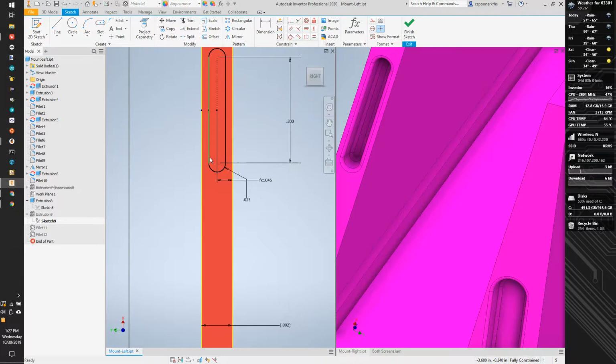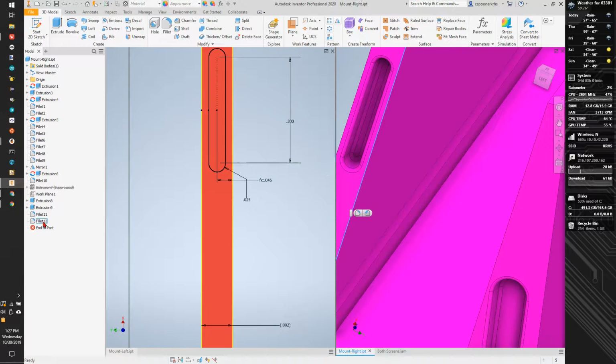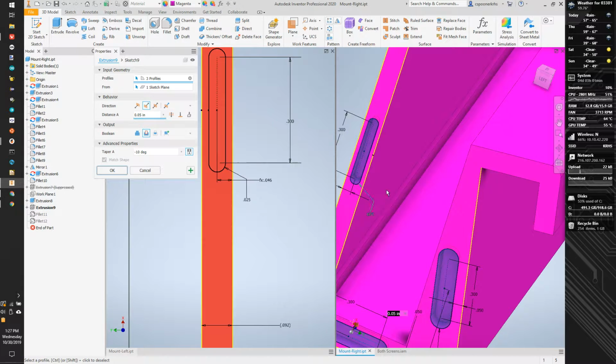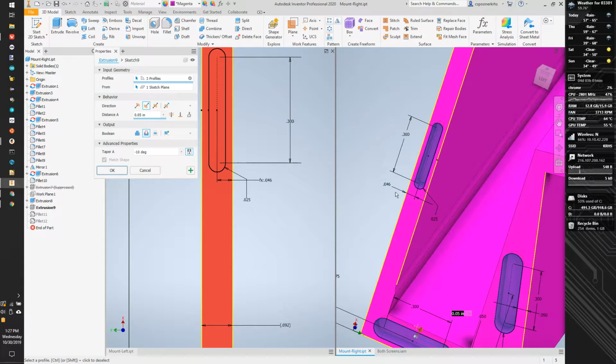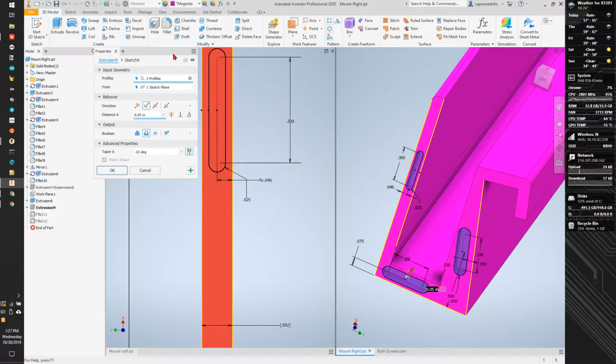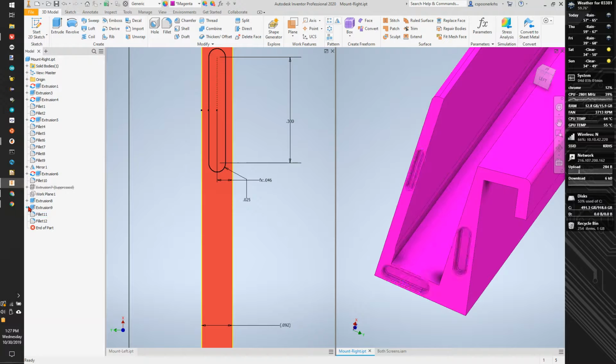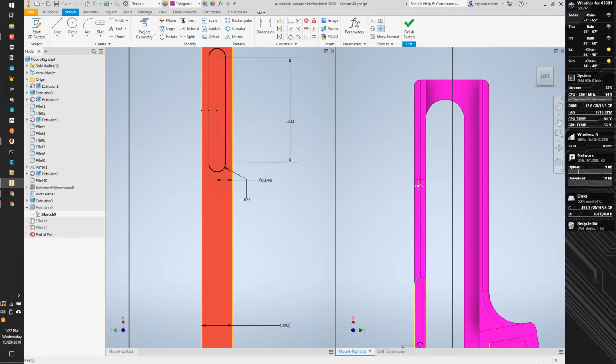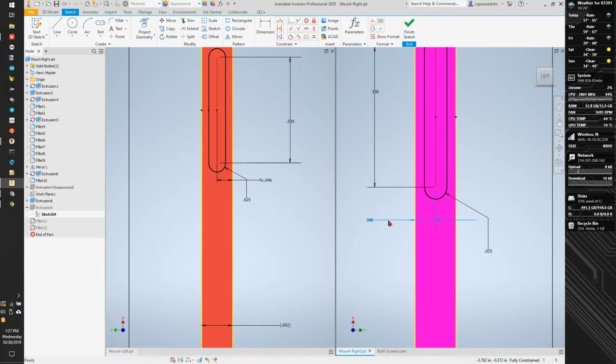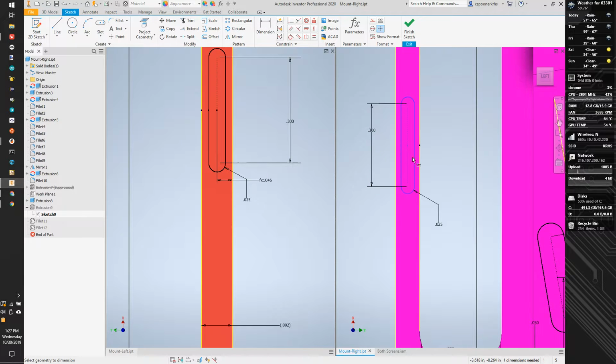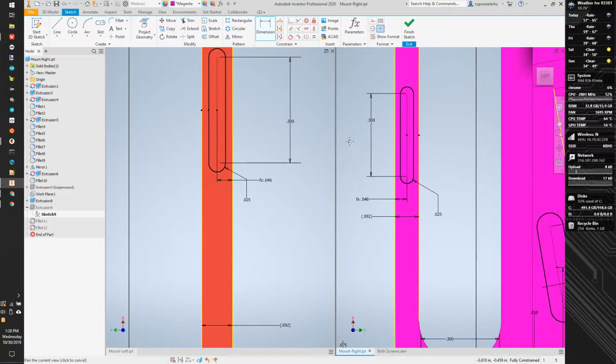And I'm going to make sure of the last dimension here in the back. And we're going to go over here, or open the last extrusion. And 0.046. Instead of doing that manually, we're going to delete this dimension. And we're going to mention from here to here, and then from here to here to be this divided by 2. And we also need to double check our length and our size.